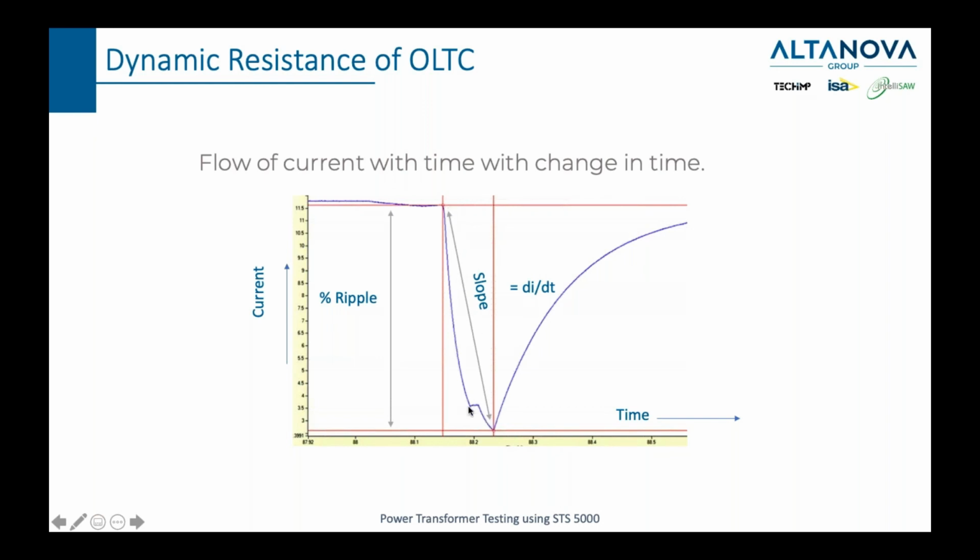Here you will see these elements which we've shown before when we are switching from 1 R to 2 Rs and then back to just 1 R, one resistor. But what you want to see is that all positions of the tap changer have the same outlook, have the same graph. If the ripple or the slope changes dramatically from one to another, then it means that we probably have issues with dirty contacts on our on-load tap changer.